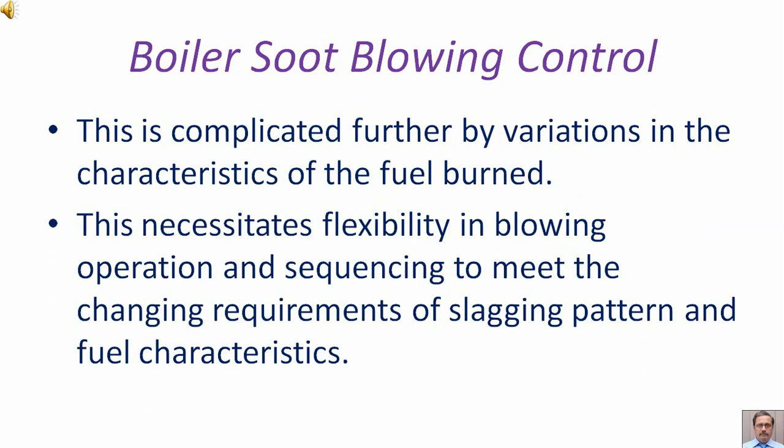This is complicated further by variations in the characteristics of the fuel burned. This necessitates flexibility in blowing operation and frequency to meet the changing requirements of slagging pattern and fuel characteristics.